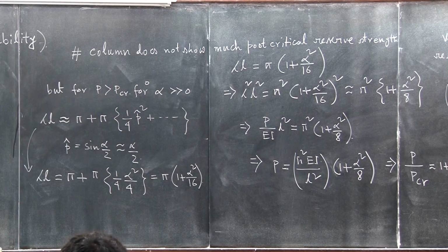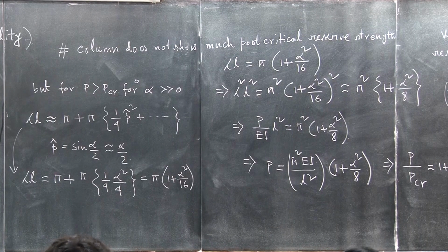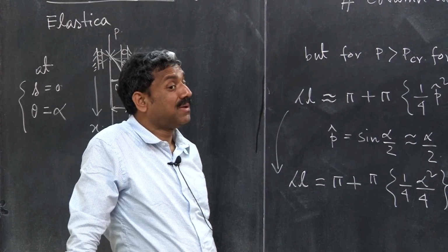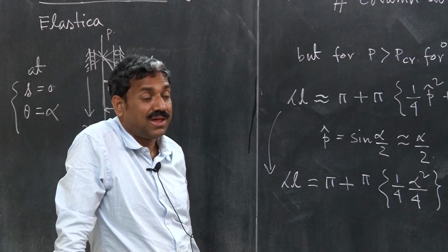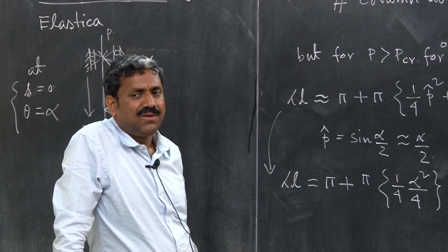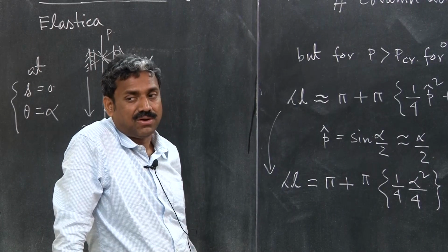As soon as the column reaches the critical load, it almost depletes its load carrying capacity. So we cannot rely on the post critical rise for design purposes. What kind of imperfection sensitivity will it show? Stable post critical bifurcation, 2/3 power law, so it will be mildly imperfection sensitive.